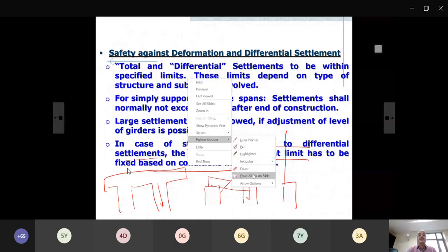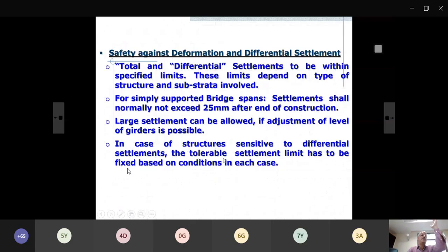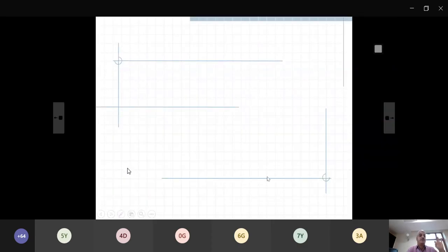A tall structure, even in substructure also, if your pile is very tall or your well is very wide, then you reduce the differential settlement limits there, because then the total shift will become very high, theta multiplied by whatever the base or whatever value you take. So those structures, you may have to fix your differential settlement and even total settlement limits on little bit lesser side. So this is what code says. It says check it from shear failure or bearing capacity consideration also for open foundation, and check it from settlement consideration also. These two we have to check.